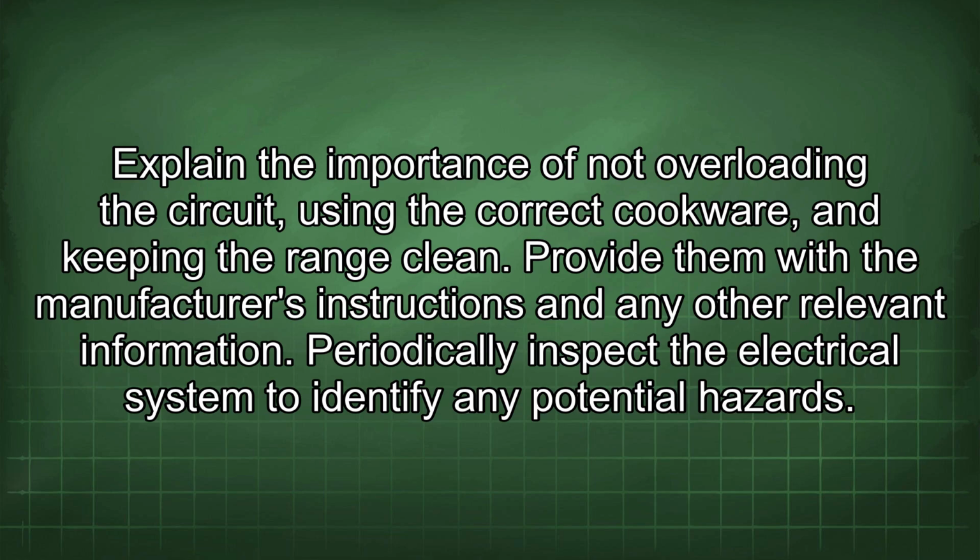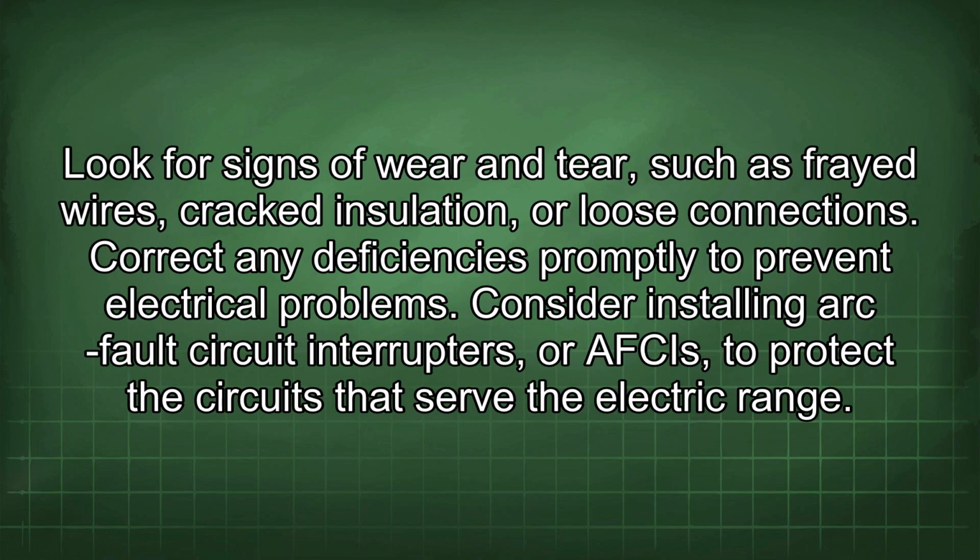Periodically inspect the electrical system to identify any potential hazards. Look for signs of wear and tear, such as frayed wires, cracked insulation, or loose connections. Correct any deficiencies promptly to prevent electrical problems.